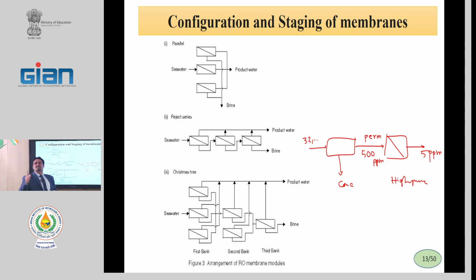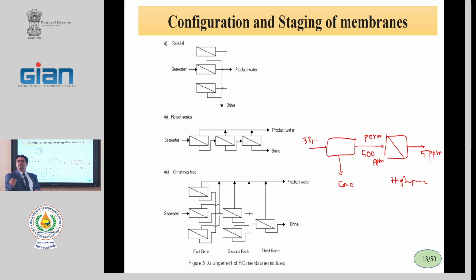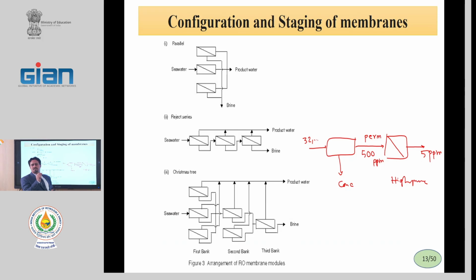And step to step, you design, and based on your water quality and the concentration of feed, you can reach different recovery. And if your data is not true, you cannot go to the second or third step.